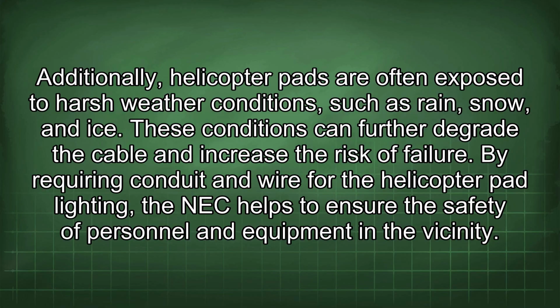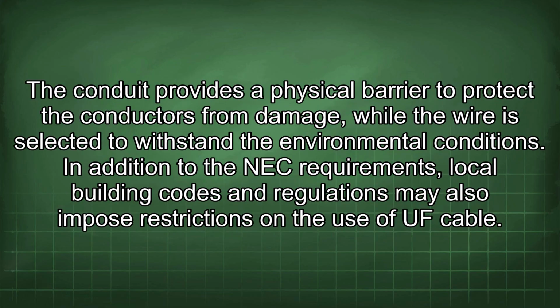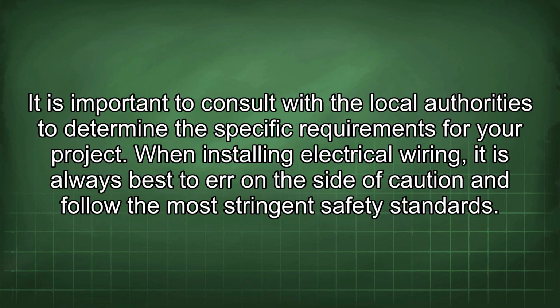By requiring conduit and wire for the helicopter pad lighting, the NEC helps to ensure the safety of personnel and equipment in the vicinity. The conduit provides a physical barrier to protect the conductors from damage, while the wire is selected to withstand the environmental conditions. In addition to the NEC requirements, local building codes and regulations may also impose restrictions on the use of UF cable. It is important to consult with the local authorities to determine the specific requirements for your project.